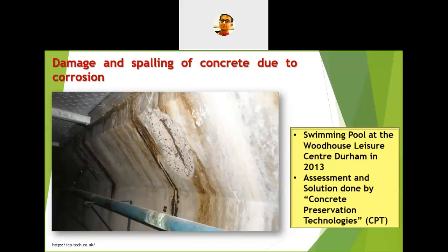So a special team came and investigated this particular problem. You can see the spalling of concrete and the reinforcing bars are getting corroded. I am annotating for you. Here you can see significant corrosion stains, and that one also. You can see how the bars are getting corroded here, and how the concrete is spalling out.